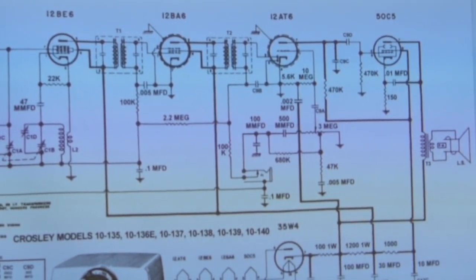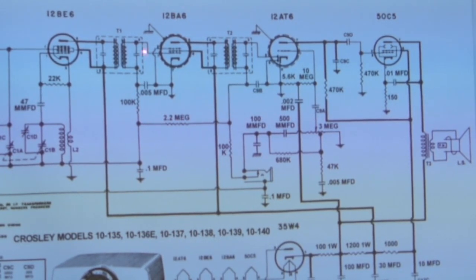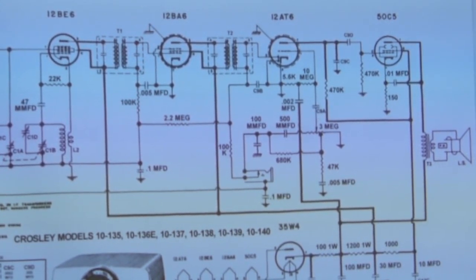Let's just assume that. We also know that the input of the radio is working, just to eliminate the possibilities. If you wanted to do a quick check, of course, you could take your signal tracer with the RF detector on it and put it here, right there, and see whether you're getting a good signal. Now, you'll have to have lots of gain on the signal tracer at that point, because there's not much coming in there, 100 microvolts. You tune it, of course, to a strong local radio source, and you're going to pick up a signal. It might be a little weak, but you'll pick it up if it's working.